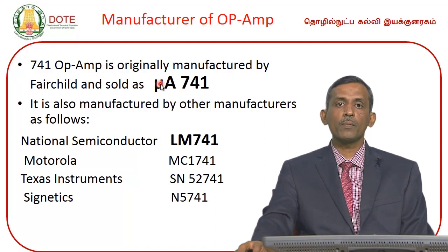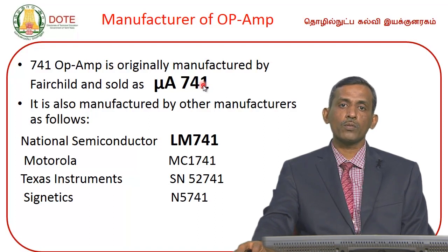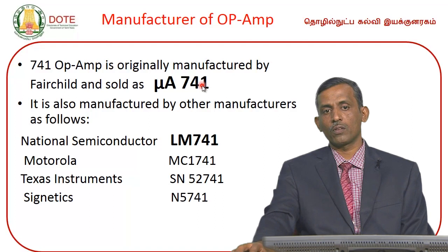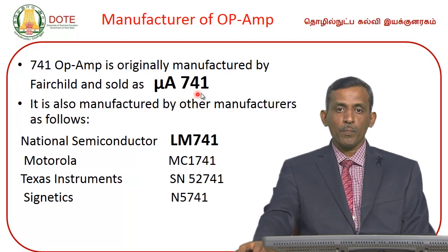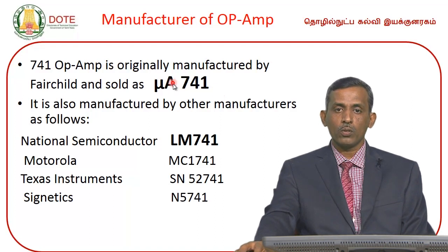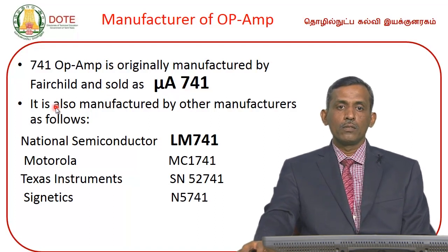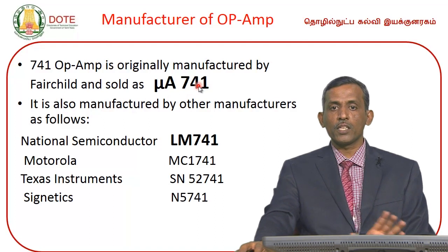That means who is the manufacturer, you can find out who made this chip using this code. This code number refers to the type of circuit inside the chip. Okay. So in MU-A741, MU-A is the manufacturer code initial used by the Fairchild company, and 741 indicates the operational amplifier circuit. Okay. Before this we saw the op-amp circuit, 4 stages of circuit. Okay.